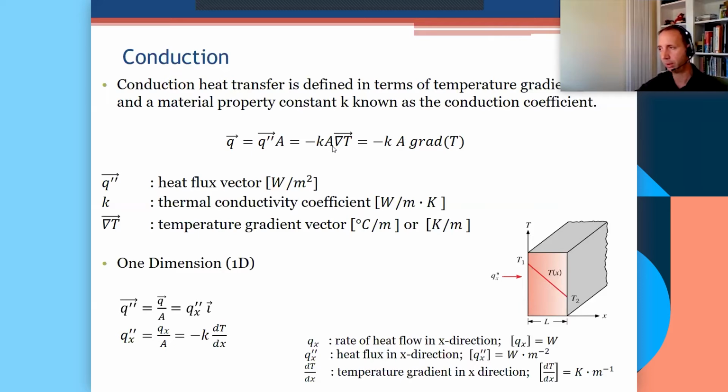The greater the area of the surface through which the heat is transferring, you see that that vector, the red arrow, is actually perpendicular to the gray surface, and it's the direction of heat flow. And the greater that surface area, the more heat you're allowing through for a given temperature difference. So that's why area is important. And when we say Q is proportional to the area and the gradient, then essentially we mean that we can say Q is equal to the area times the gradient multiplied by a coefficient of proportionality.